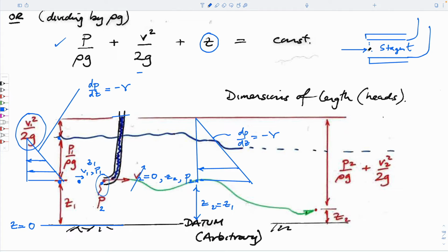So it has to come here. The velocity here has to go to 0, and it will physically go around it. Okay? And this is what we call a stagnation point. If you draw the streamlines for this point, the streamlines individually will part, like the parting of the Red Sea, around this. This will be the flow field. And of course, the port that I was talking about measures the pressure at this point here, and this pressure here will actually be the true pressure at this point because it's still going at velocity V1, right? This is still V1. Yeah, good question.